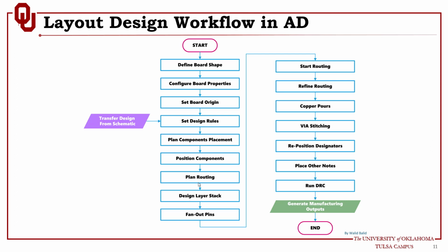Start with differential pairs. Make sure to keep enough space around them for length matching, or you might match them at the beginning if you want, so you know what space you need. Then start with routing data buses. Data buses should be routed together.